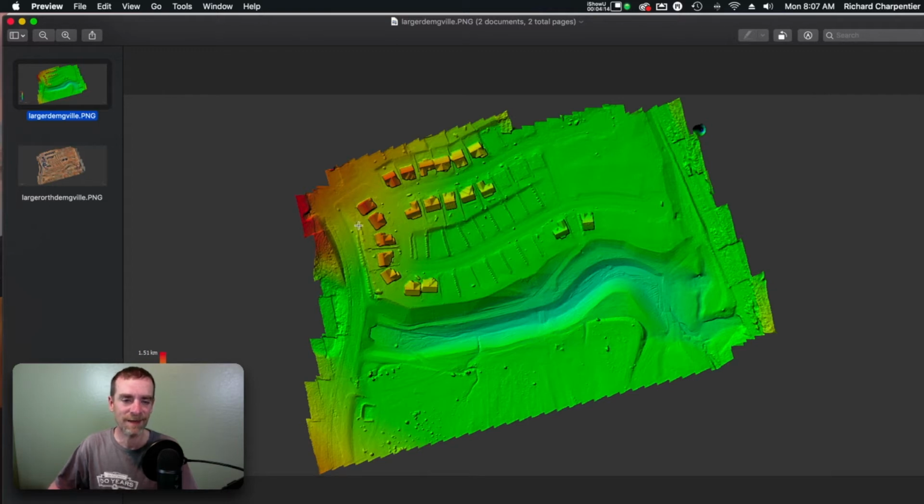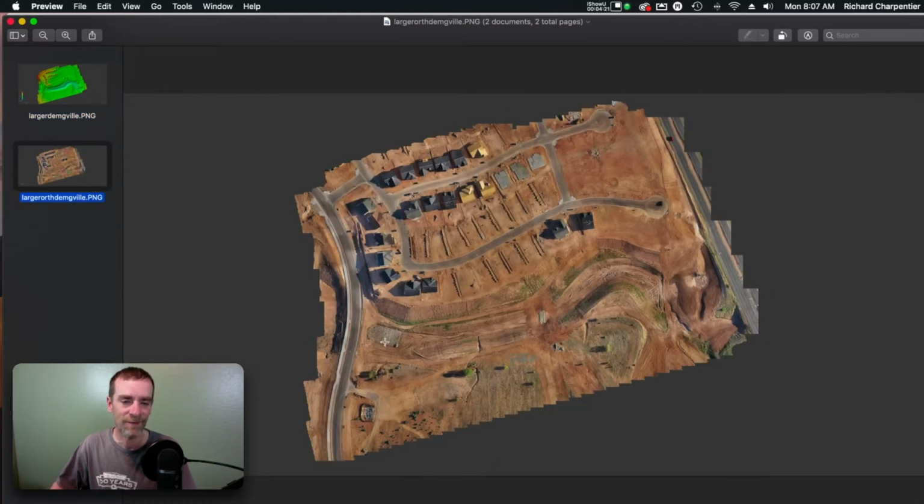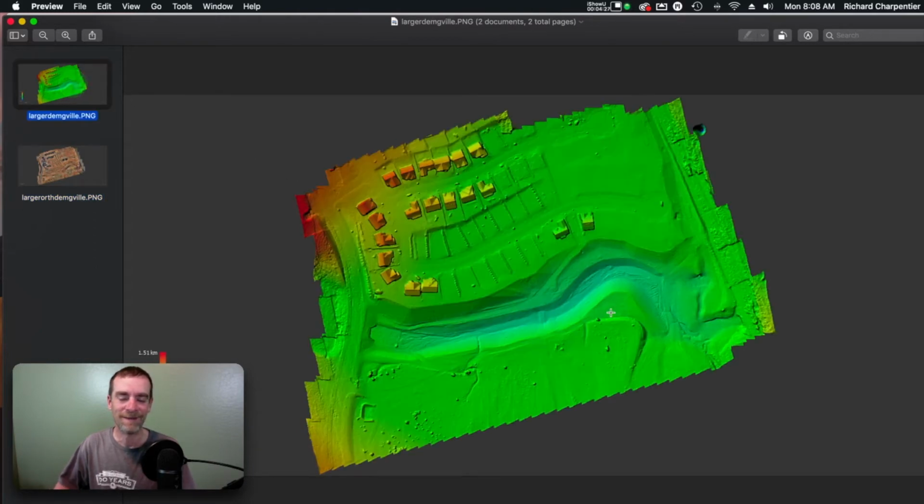And so from this height of land here, I'm figuring drainage will be going down this way, and they've got the culvert right down there. Let's move back over, and you can actually see, this is going under the road. So we know where the washes are going to be, and the digital elevation models really help demonstrate that. It gives people a great idea as they're planning and building the projects if they need to rethink where water runoff is going to be going.